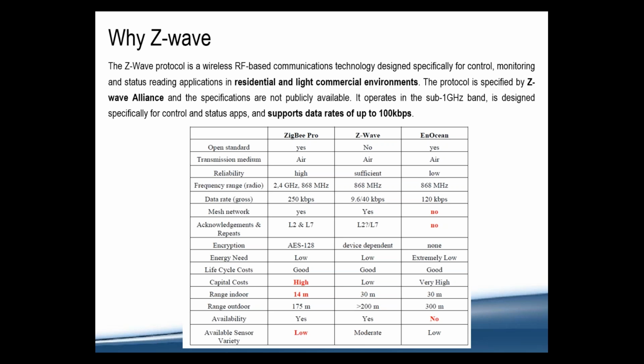But the main benefit is that we have a commercially available solution supported by the Z-Wave Alliance, which is a mature alliance that focuses mainly on the commercialization of the solution. There is an active community providing support to the deployment of that type of solution. Another main benefit is that it's a mesh protocol, so we can easily scale to a building environment. We can put different devices, and all of them get connected.